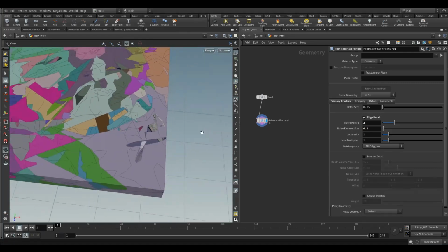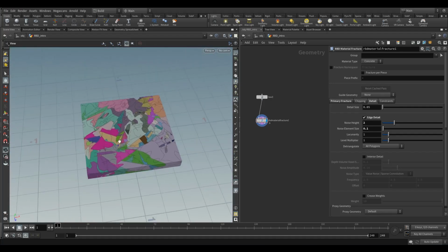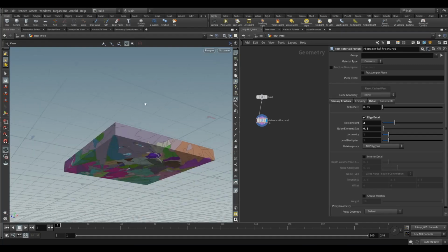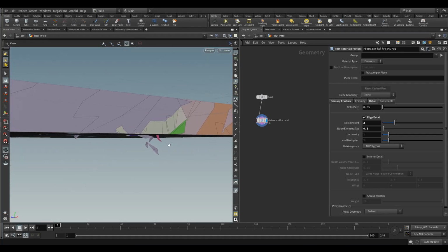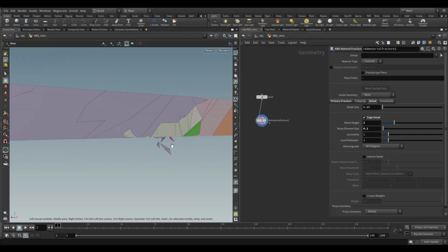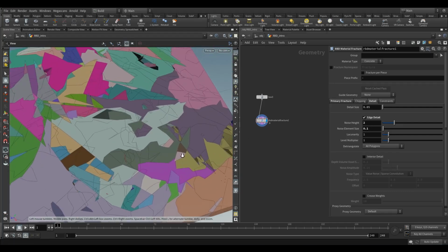There we go. So yeah, after forcing it, you start to get weird results. It breaks on more complex geometry than just a box. That happens much more easily. And you can see here we start to get a cutting plane coming out into our results. That's from me forcing it, because I've got ridiculous results, but it does happen more easily with more complex input geometry.